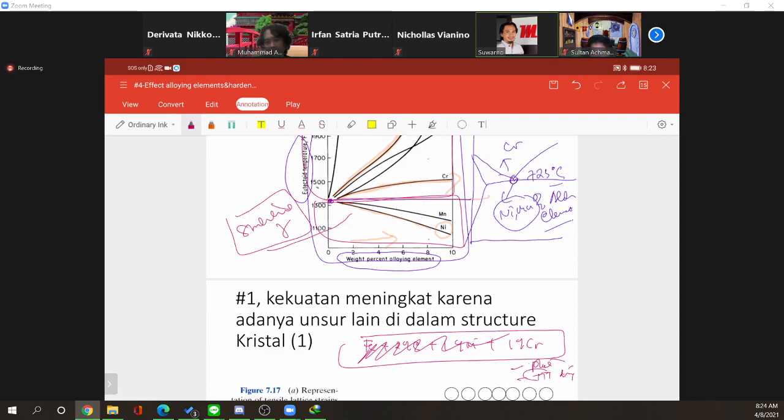It means that every alloy will have its role as either a ferrite stabilizer or an austenite stabilizer. If we mix both, then there will be a total effect, which is not really cancelling each other out, but there will be a total effect. And how we know it is by looking into the individual phase diagram. So it's like a cycle now. The thinking is like a cycle.